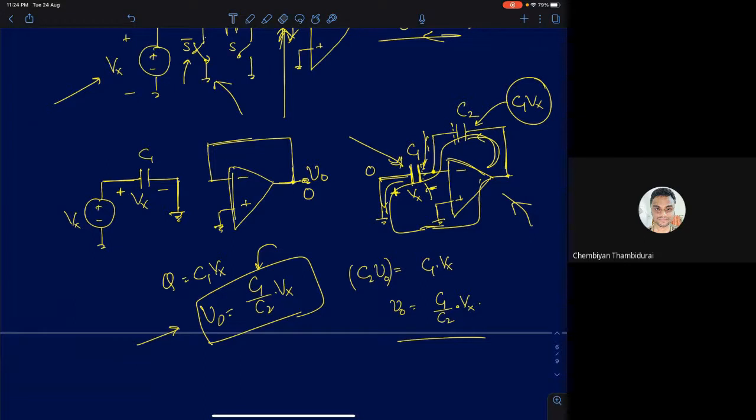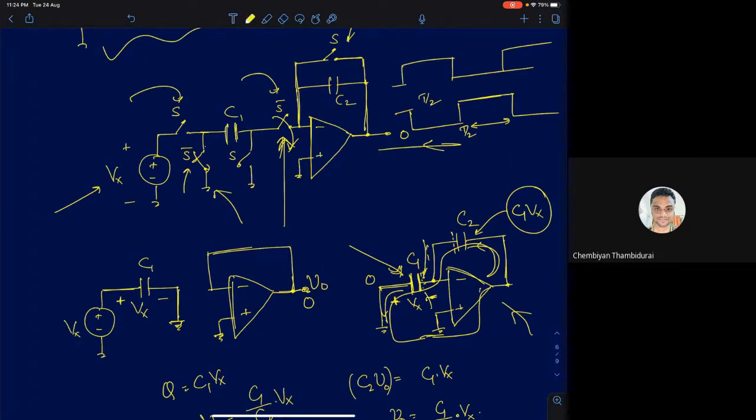Okay, but now if you see, there is no resistive loading in the circuit. I've completely removed resistive loading. You're either seeing the unity follower mode or you're in a capacitive load. The load is a capacitive load. What's the problem with the resistive loading? Let's say I had a resistive load. What reduces if I have a resistive load? The DC gain will reduce, right? The resistor will start loading the output, the op amp's output, the amplifier's output, and that will decrease your DC gain. That problem, the DC gain problem, doesn't exist here.